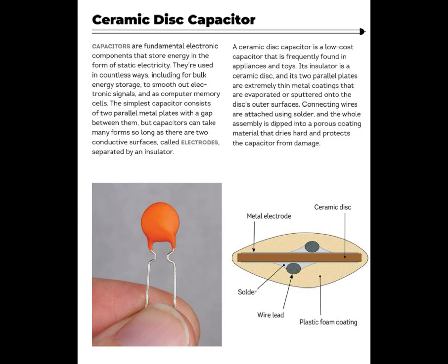The advantages of it are as follows. Number 1 is temperature stability. Class 1 capacitors maintain capacitance better across temperature changes. Number 2 is low loss. They exhibit low equivalent series resistance, making them ideal for high frequency applications. Number 3 is the size, typically compact, allowing for space-saving designs in electronic circuits. Number 4 is durability, resistance to moisture and mechanical stress, making them suitable for harsh environments.